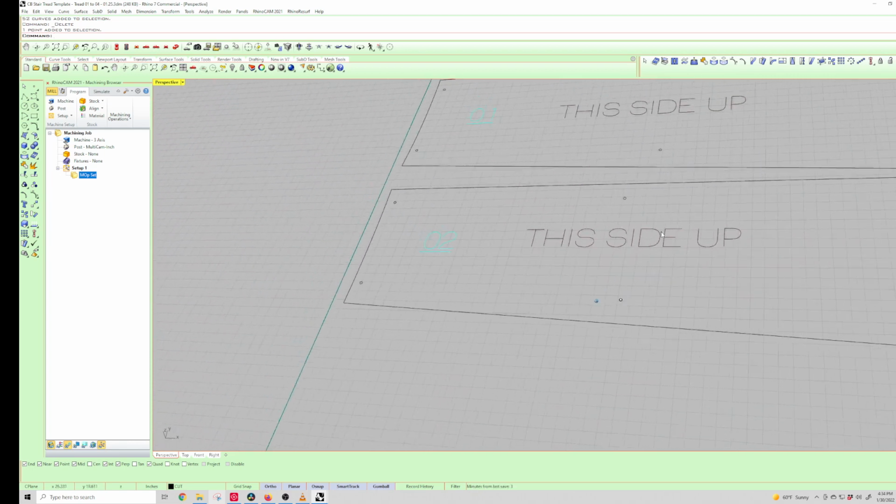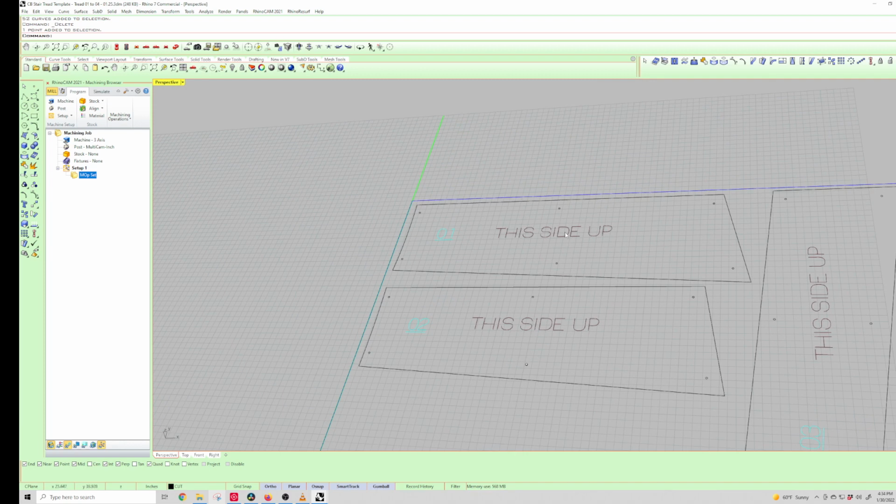But to start off with, the first thing that we're going to do is engrave all of this lettering that's in here. So first we go up to machine operations, and we're going to click on the 2.5 axis button, and these are the different operations that we do. Typically what we use are engraving, profiling, pocketing. That's pretty much what we use. Probably 95% of the time, 99% of the time, those are the three tabs that we'll use. So to start with, we're going to do an engraving pass.